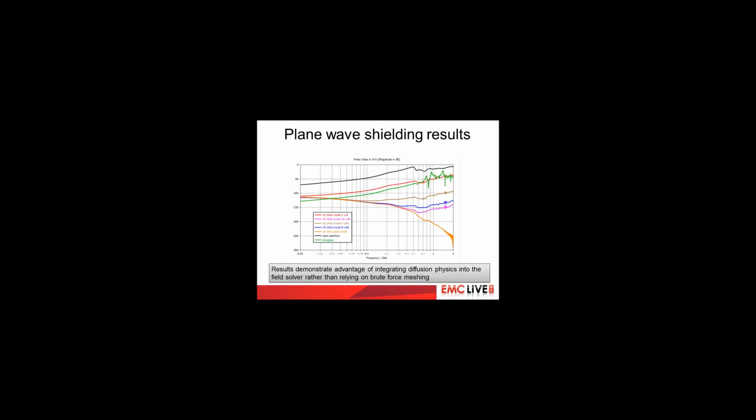The reason is that at high frequencies, the skin depth is very small, and a very fine mesh is needed to capture the current variation accurately. The orange curve shows the TLM thin panel model, which is in fact the most accurate solution. Unfortunately, it is also the least expensive in terms of computer resources. So this just highlights the difficulty of modeling the correct frequency dependency of composite panels by brute force meshing. You really do need a special material representation to handle this efficiently.